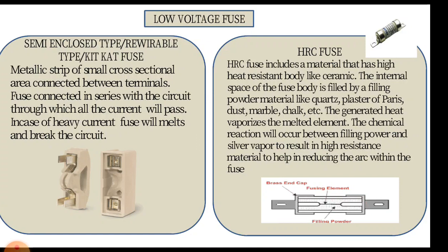Then HRC fuse, that is high rupturing capacity fuse. It consists of a heat resisting ceramic body. It has a metal end cap which is welded to the silver current carrying element. The space within the body is filled with a filling powder. The filling powder may be chalk, plaster of Paris, marble dust, quartz, etc. It acts as the arc quenching medium.